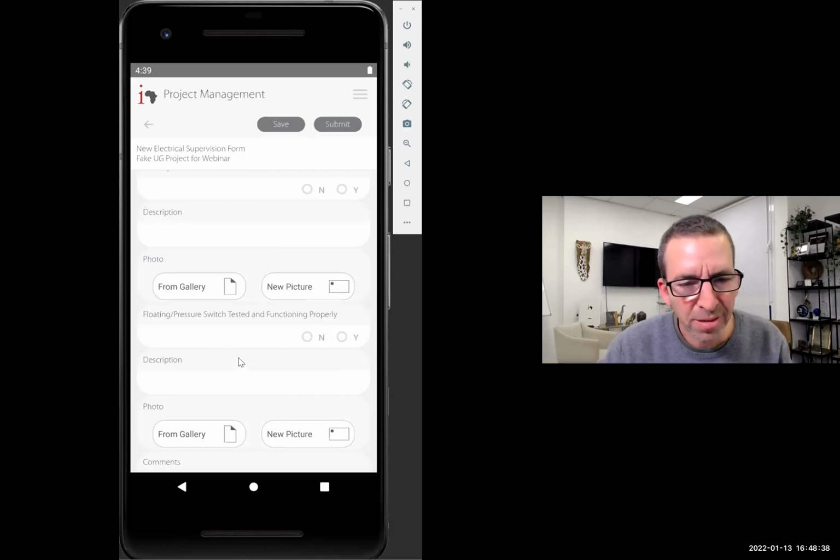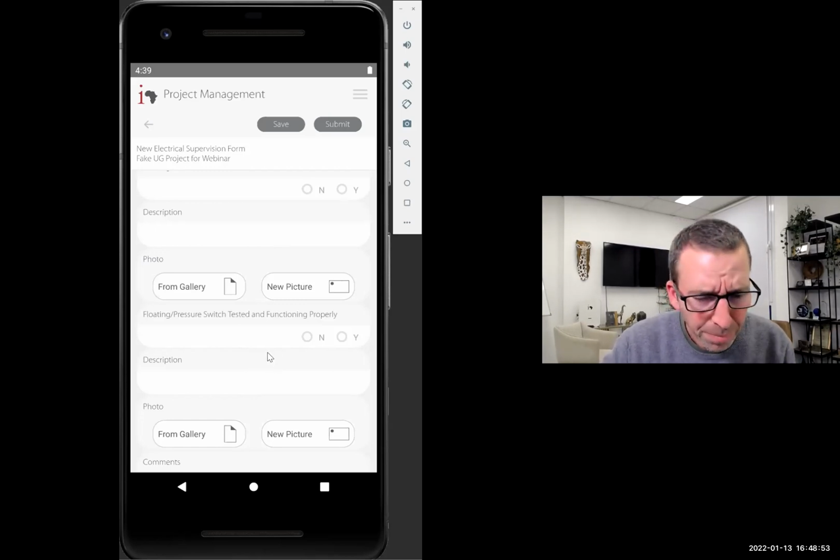This check means that when the tank is full, you see that the floating switch or the pressure switch disconnects the pump. It's also the electrician's role to connect it and to adjust the pressure switch. So in any case, he will have to do it.